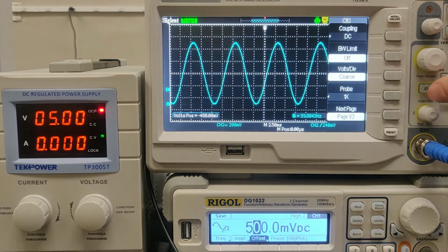So let me just get rid of our input because it's really not changing. Well, it's being shifted up, but the waveform really doesn't look different. Now we are getting an exact one-to-one correspondence between our input and output signal. By introducing a 500 millivolt DC offset, we now have our input and our output signals looking identical.